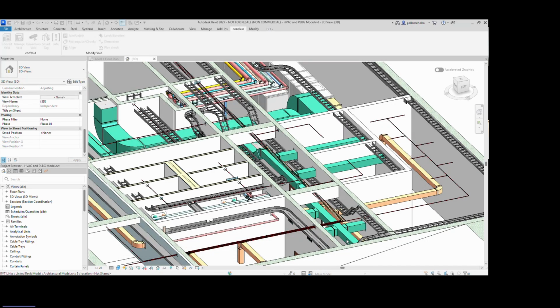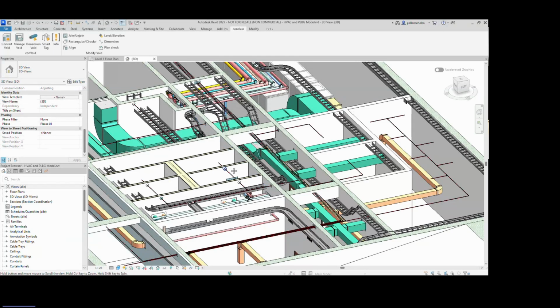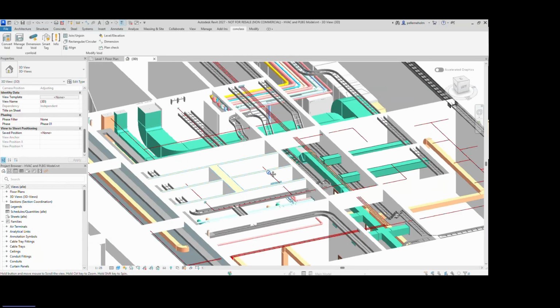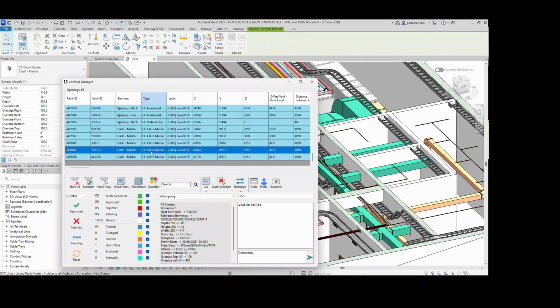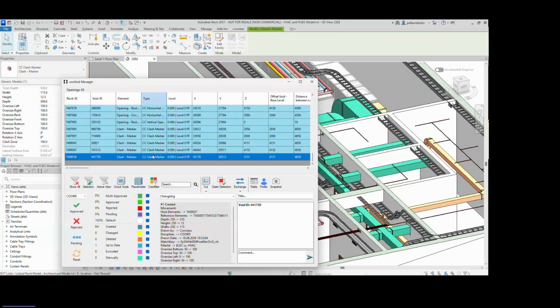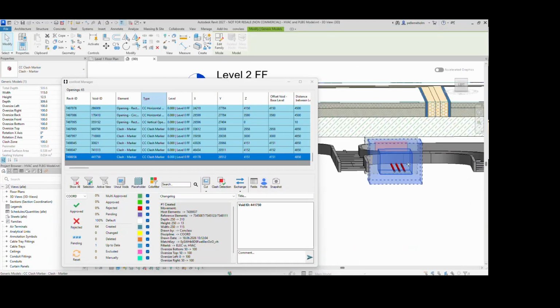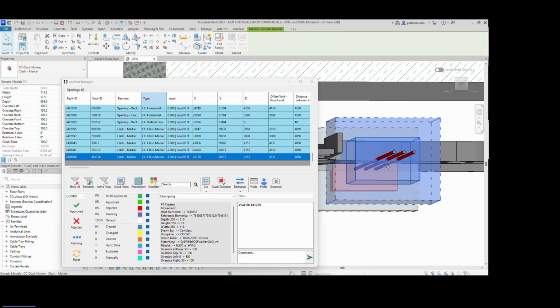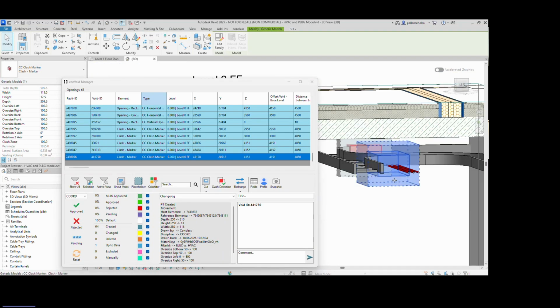Also, you can, of course, exclude some elements using a reference view, but that's probably known from the creation of openings. So let's run the clash detection again. Here we also have 3 near clashes. I couldn't see them directly now, but let's have a look. All right, here it is. A clash between the cable tray and the pipes.